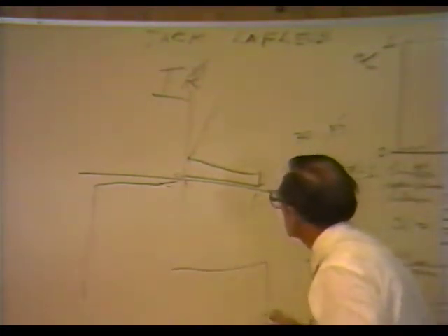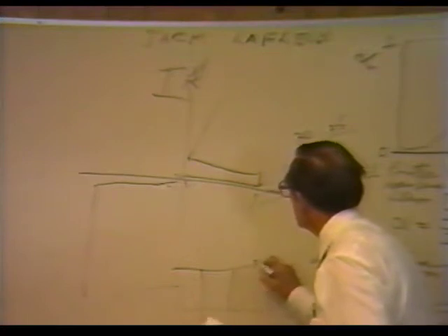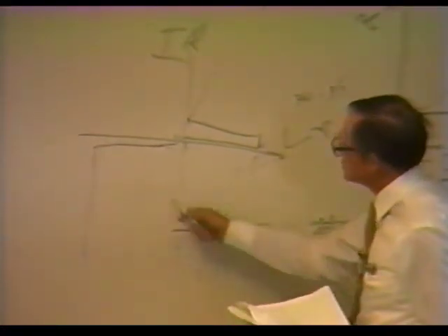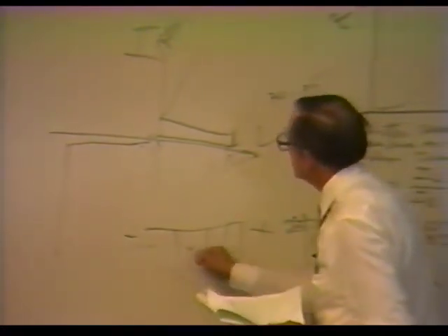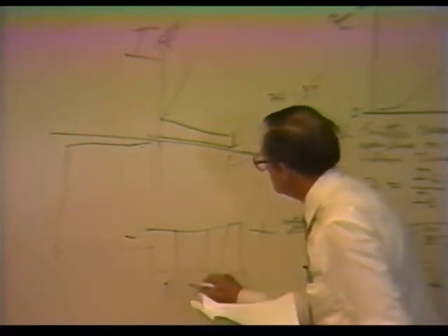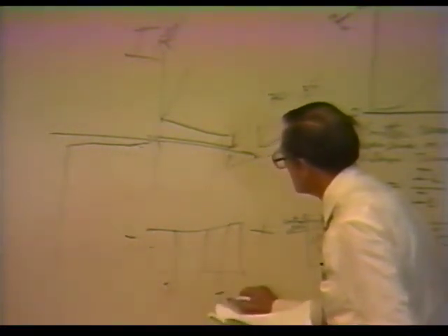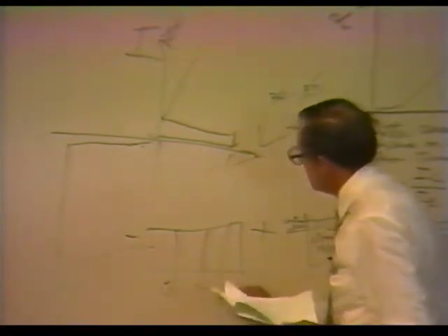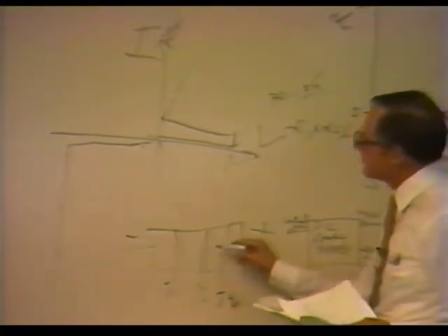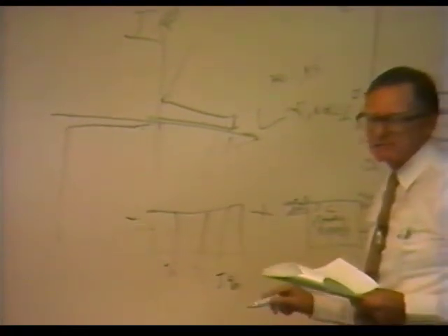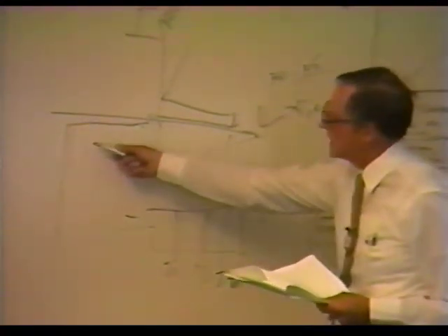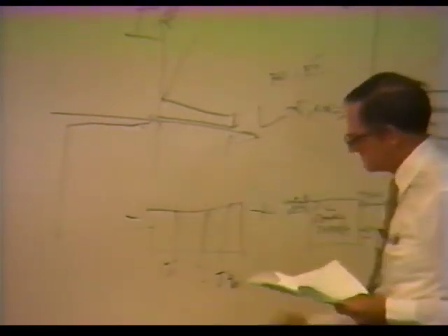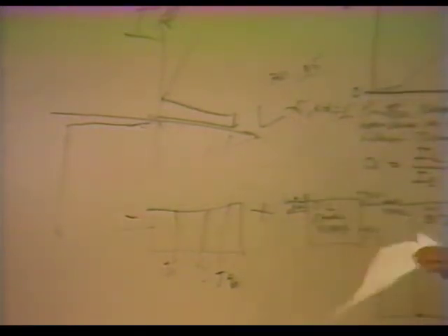The reason for that, very quickly, and we'll write this up, is that the junctions that are sustaining it in the reverse direction are the J1, J2, which are reverse biased. This junction is forward biased, J2 is forward biased, and we do not have a feedback mechanism where we can keep the device, the SCR, on in the reverse direction as we do here. Let me see if there's anything else.